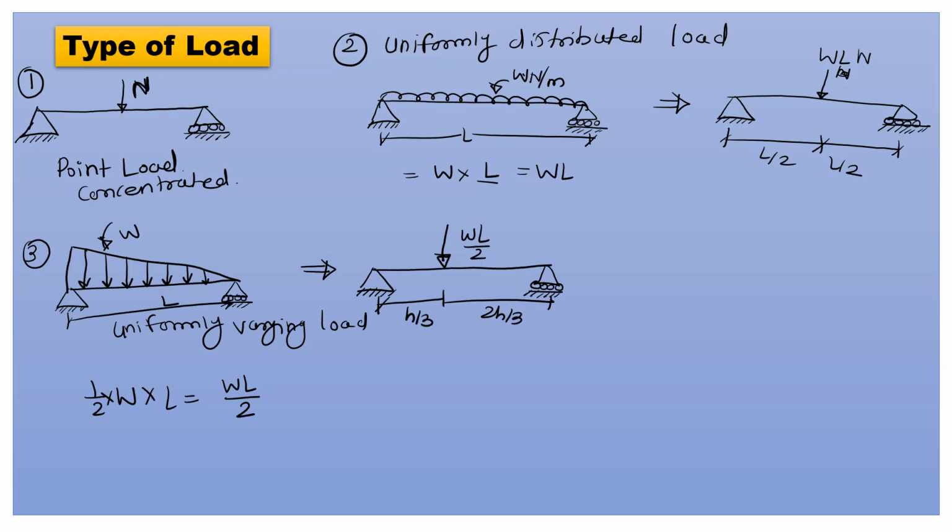There are two very important points. We will discuss them further in later sessions or slides, but this point is important, so I tell it here. Note that point. First point: the bending moment at a hinge is 0, meaning at a hinge point the bending moment is always 0.